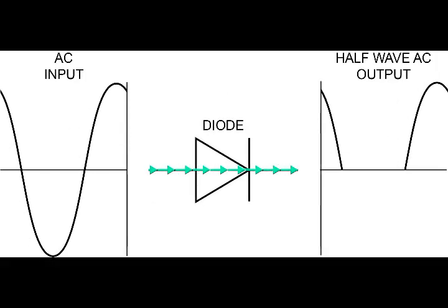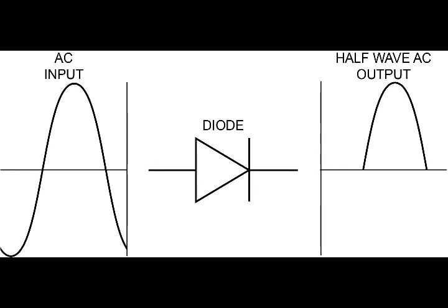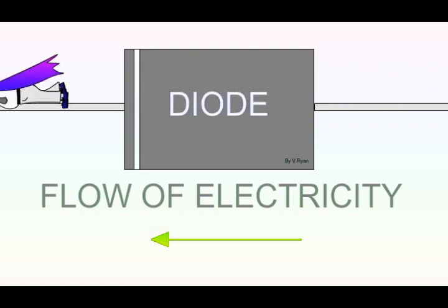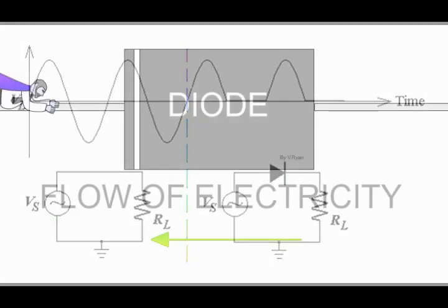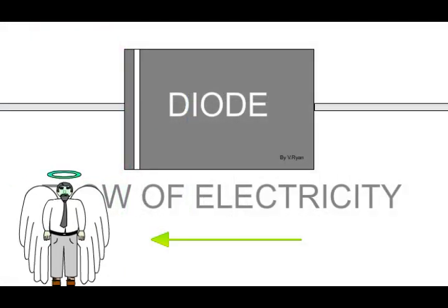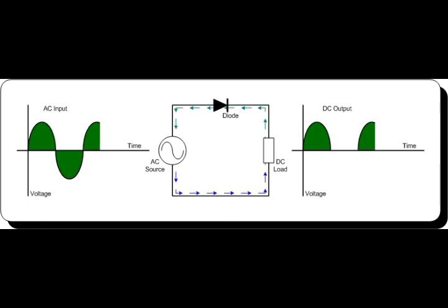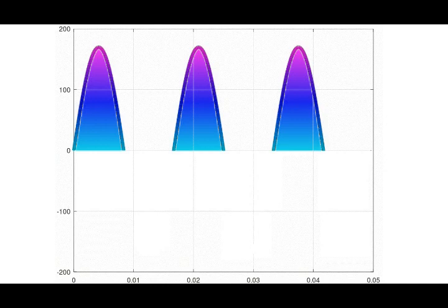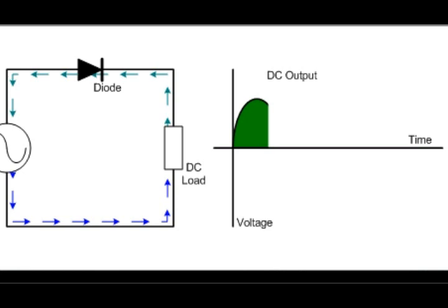This PN junction converts half the waveform of a bidirectional AC source into a unidirectional waveform. For example, when the diode is forward biased, it can pass a positive half cycle, while when the bias is reversed, it removes the negative half cycle. A single-phase half-wave rectifier configuration passes the positive half cycle of the AC source waveform and removes the negative half cycle. A pulsed DC output means that the equivalent DC value across the RL load is the average value of only one half sine wave.